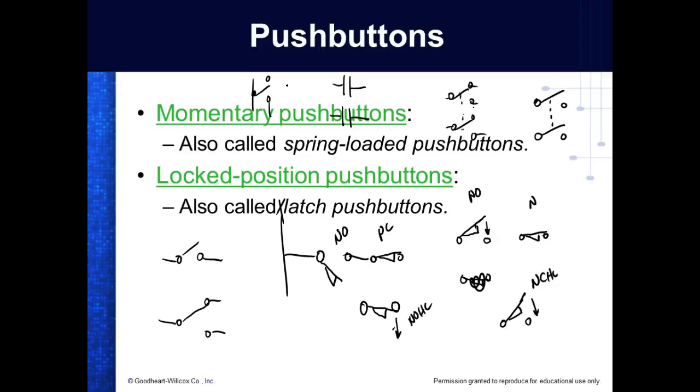Here's the diagram for it. You can look for it. Sometimes they put it on the top. It's very confusing on the top. So what you're looking at there is a triple pole, a 3-pole, double throw. I could show you that. I think it makes it easier. By the pole, I mean the side of the switch that's connected where it pivots. That would be the number of poles. And the switch on the other side is what you're actually switching from. How many directions can it switch and control a different circuit?